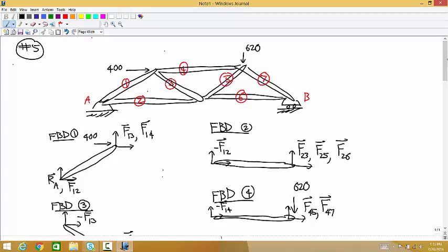In that case, you would have what? 1, 2, 3, and then, well, I guess 7. I think that's a system of 7 equations and 7 variables because you just need to solve for those. And then maybe you might have to isolate the whole thing first, so maybe it's 10 and 10 or something. Yeah, but yes, you can do it as a truss. So we can do the external loads first and then do internal loads? Yeah, you can do the external loads first, like the reaction at A and the reaction at B, and then from there solve for the tension or compression in each one of those.